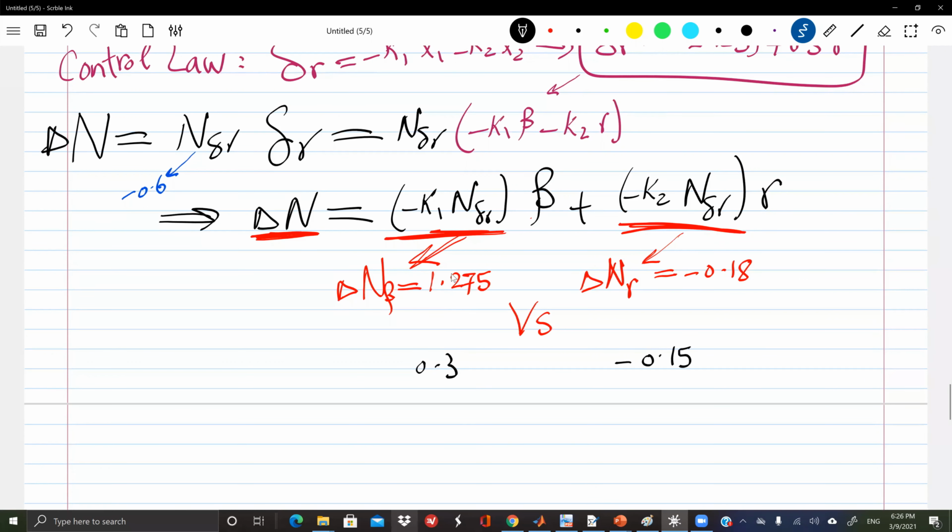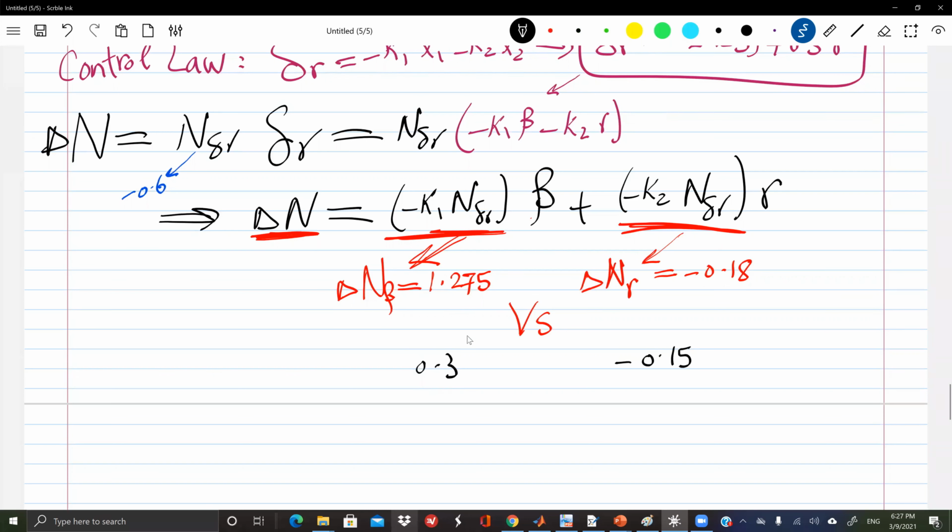So look at that. How much additional stiffness are you adding? It's 4 times extra. So it's as if I'm multiplying my yaw stiffness by 5 times, because the total will be the addition of the two, which I could have done by doing what in the geometry of the airplane? Increasing the area of the vertical tail. Exactly, multiplying the area of the vertical tail 5 times. Again, these are some of the requests that you will get fired if you ask your chief engineer to do.